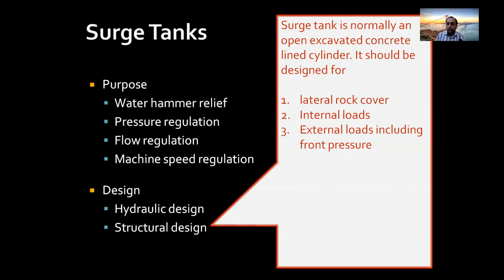If you are providing a lining, it is not designed for the rock load. For rock load, you have to provide rock bolts and shotcrete or ribs.